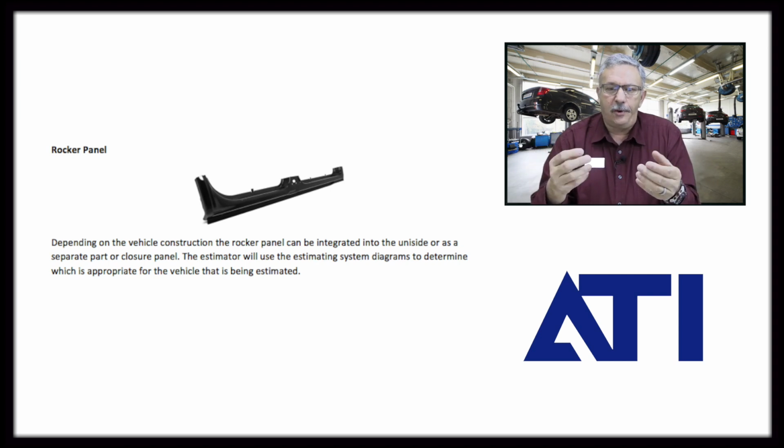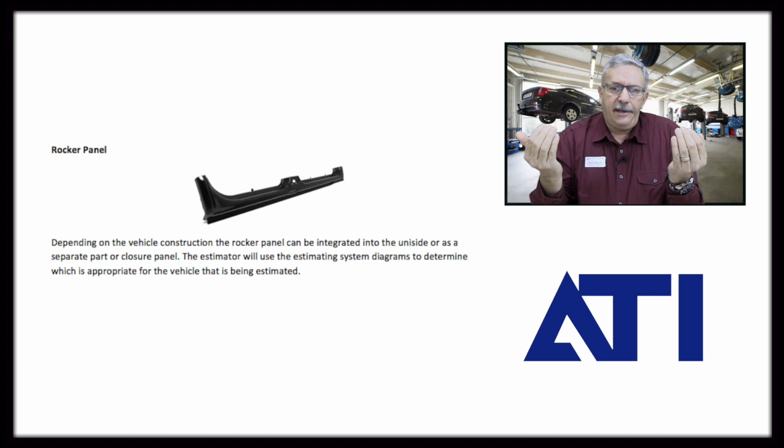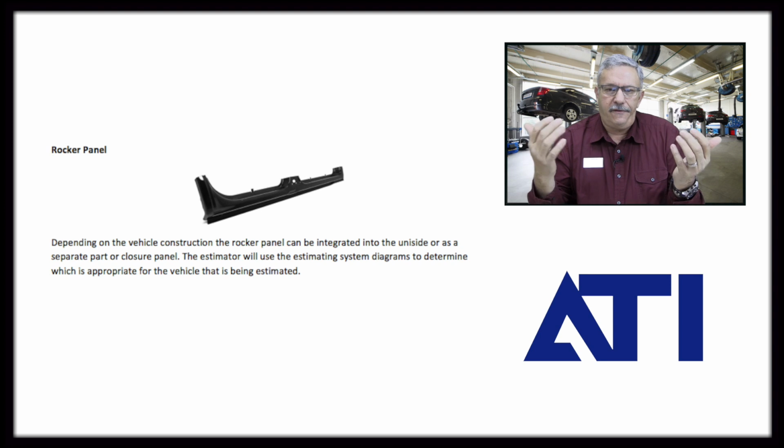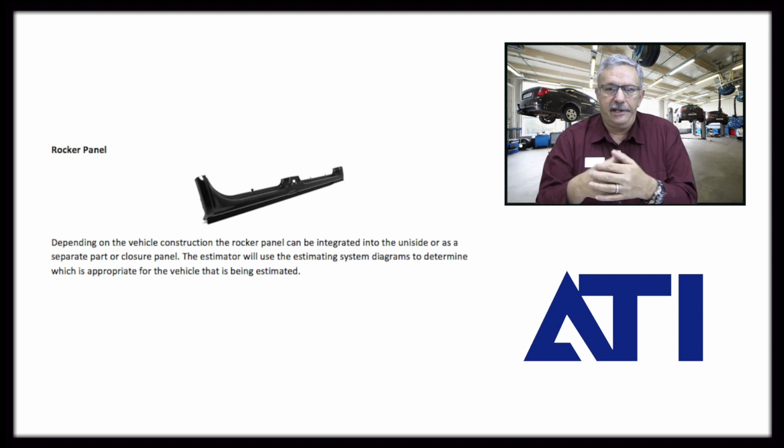So those are the two things, but whenever we're putting on a closed box section, this is essential, because what will happen is, again, all those places where we welded, they immediately become corrosive hotspots. So any electrolysis that's going through the vehicle will go to that area because it's open, and then you have humidity, moisture that's created through condensation. All of that will start attacking that bare metal. So if we don't put that corrosion protection in, that hot spot then will turn into rust. Eventually you get rust perforation, then you have a warranty issue with the repair.